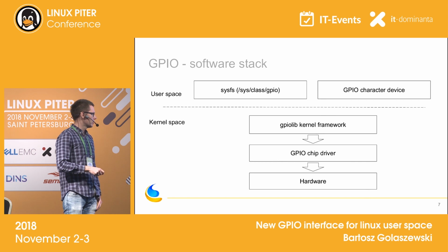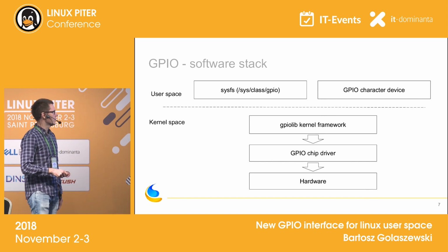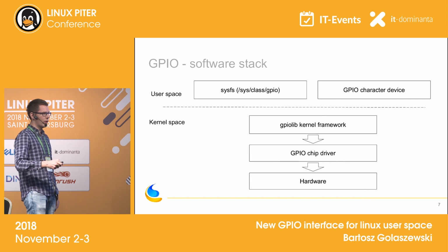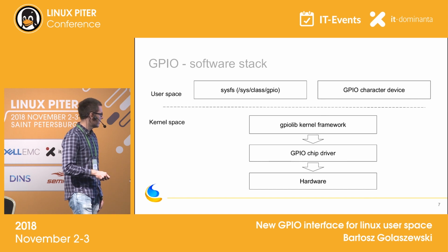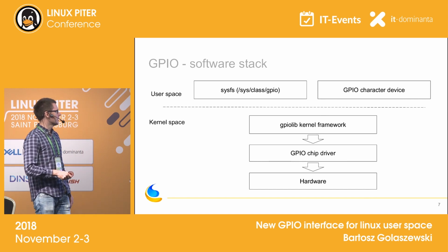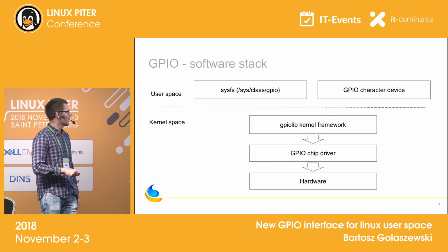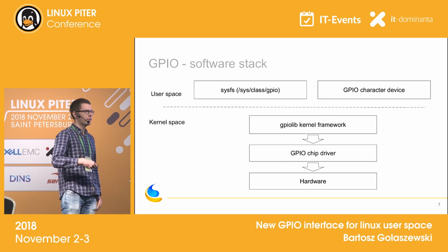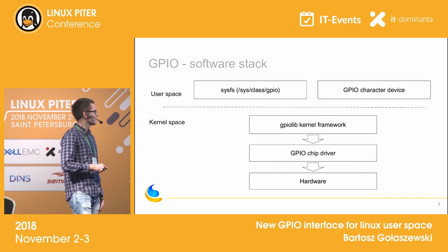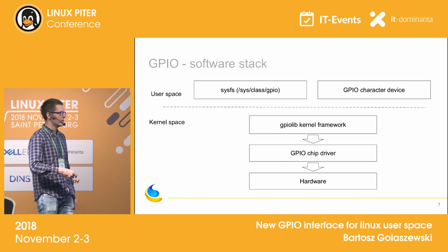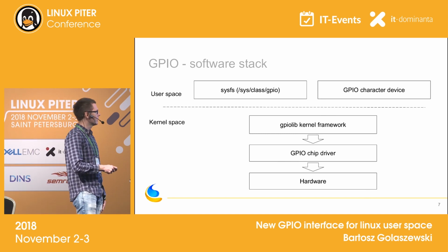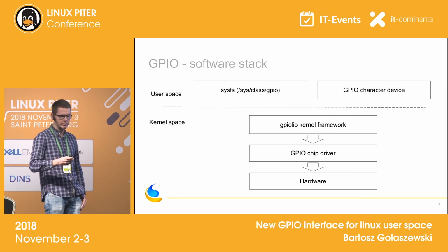The GPIO chip driver talks directly to the GPIO chip controller, either by poking registers if it's register mapped, or by sending I2C messages, and then implements a certain interface that is defined by the GPIOlib kernel framework. So it implements all the functions that the GPIOlib framework expects, which in turn allows the GPIOlib component to export a uniform API for in-kernel users and for Userspace users, so that we can use all kinds of GPIO chips by the same set of operations.